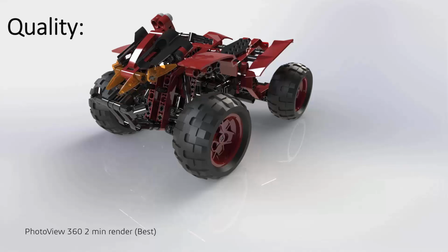But as we move these things down, you can get quicker renders, a minute and a half on better settings, but you can see that there's quite a bit of noise starting to be introduced into the image. If you snap down to good, you can see most of our reflections have gone and we're starting to get quite a bit of noise. So it's not really an acceptable image here, even compared to better. But you can get quick renders, just not of the same quality, in my opinion.